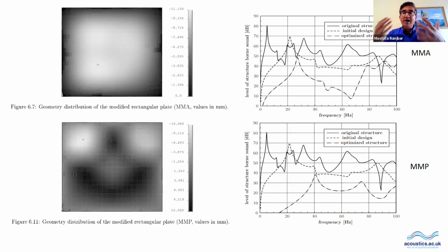It just provides the idea of how you can change the geometry of the shell plate so that you can reduce the radiated noise according to the type of excitation, when you have non-symmetric excitation, the shape of the boundary condition, etc. Here you can see the result from the mid-range multi-point method.